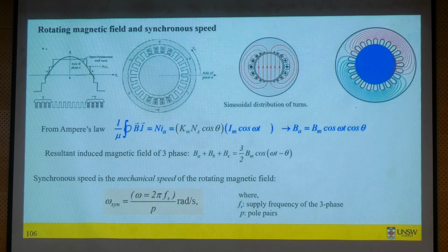Here you are seeing a two-pole machine without the rotor. You're simply supplying the three-phase current induces a rotating magnetic field. Okay? So for PM machine, same thing. You will be applying the three-phase balance current, but via a inverter.